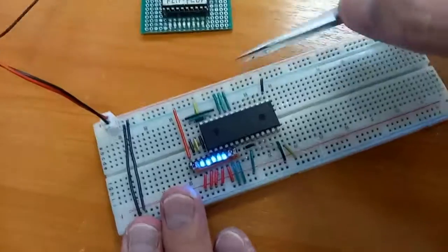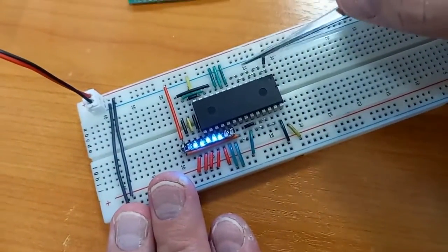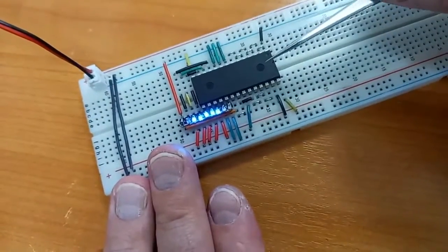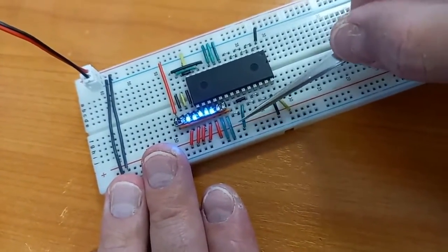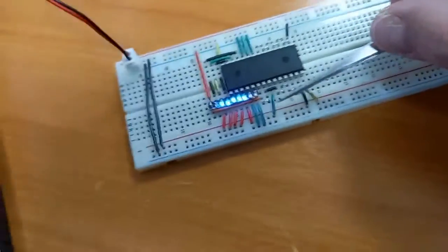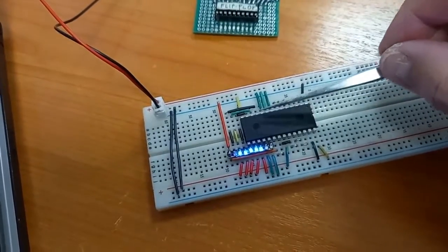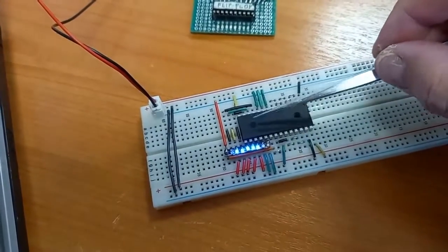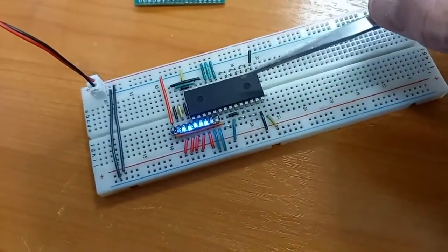Now at the address bus we need to have 0. Address is 0, and now it is 0 because all the address pins, address legs, are connected to 0. Now we have disabled the output, so it's not outputting at the data bus, but it's inputting. At the data bus it will read our number, and address is 0.